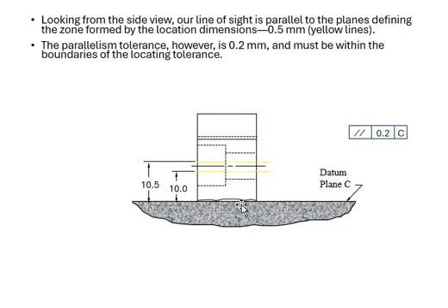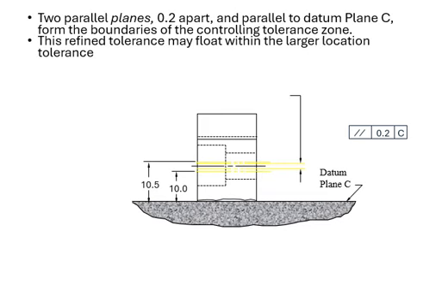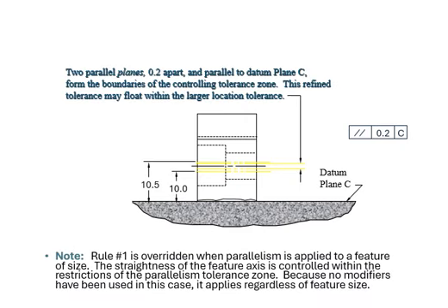So with the exaggerated surface right there, we're measuring this axis against that datum plane C, your sides, and then your tolerance zone, which is this guy, and that's going to be 0.2. When you look very carefully, you can see two different zone sizes, and then also the parallelism tolerance, just right there. And now we can see this axis is definitely within this 0.2 parallel planes.